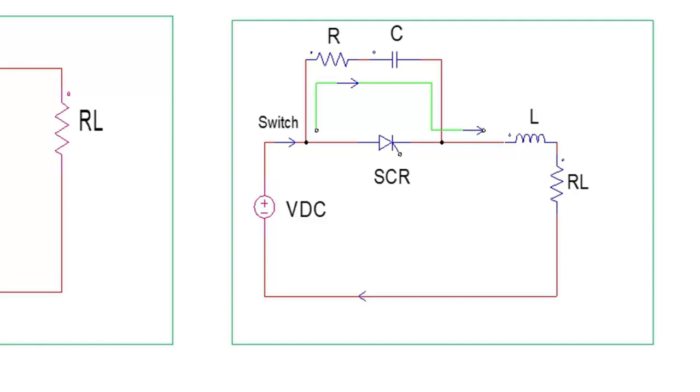So for dVdt protection, capacitor is connected in parallel with the SCR. This is the property of the capacitor, that initially it will provide minimum impedance path and will absorb the power, allowing more current. And then finally, when the voltage across the capacitor is equal to the supply voltage, then current will be zero. So this dVdt spike is absorbed by the capacitor. So the capacitor protects the SCR from high dVdt.